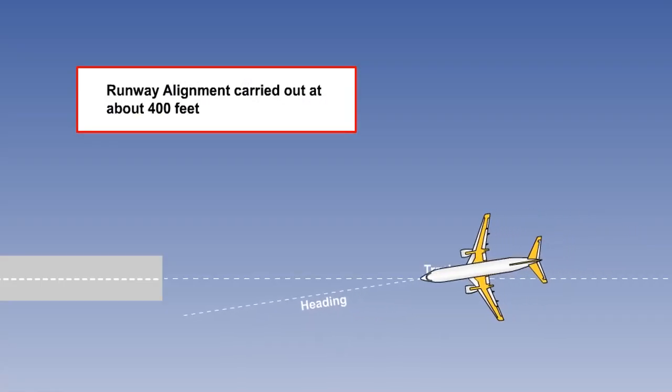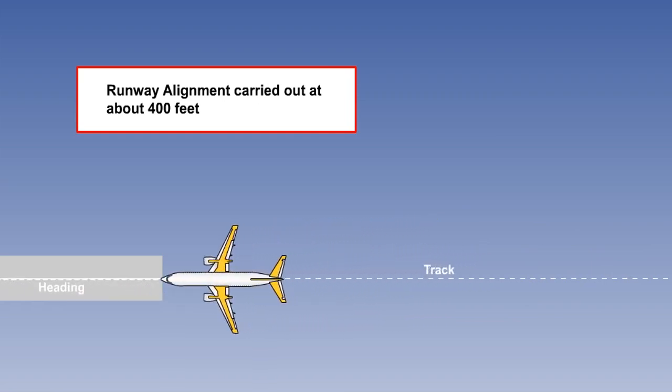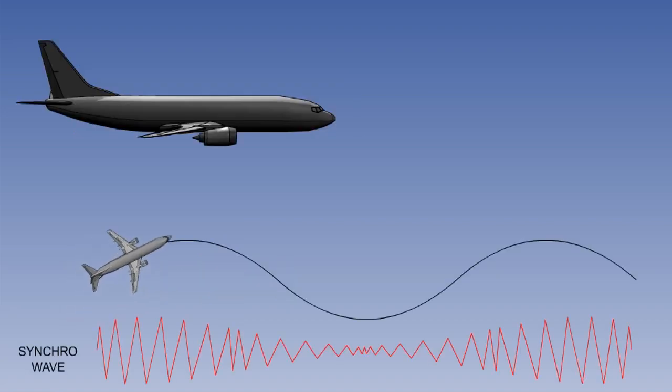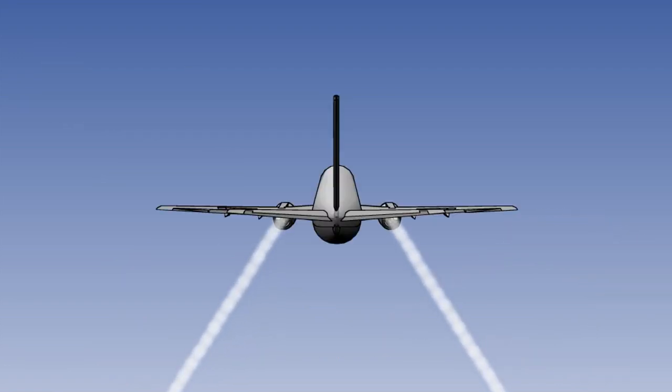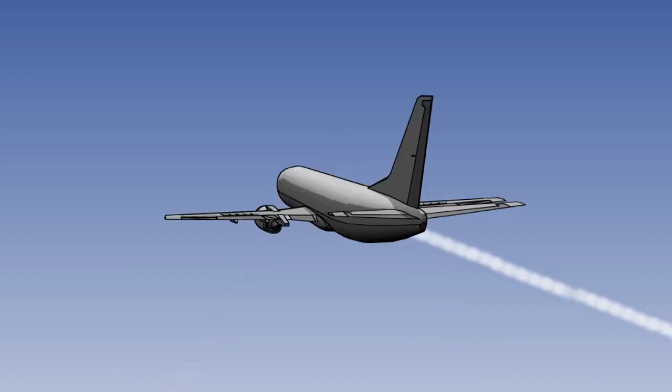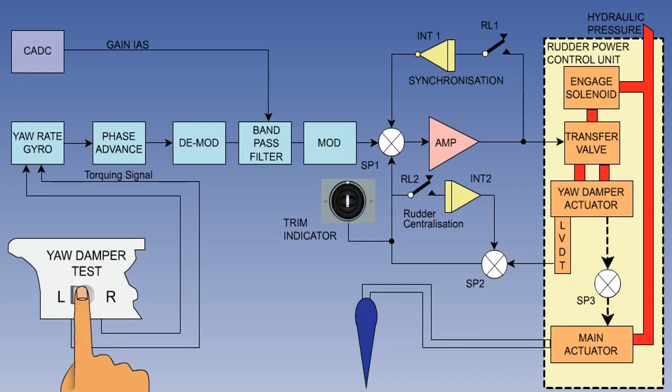During this lesson, you have learned about the yaw damper systems and the reasons they are used in aeroplanes, which is to suppress Dutch roll. You examined the components of a typical yaw damper system, including the Dutch roll filter. Next, you observed the yaw damper in operation, including the test function and the way it can assist during engine failure and normal coordinated turns. Finally, you learned about the controls and indications in the cockpit.